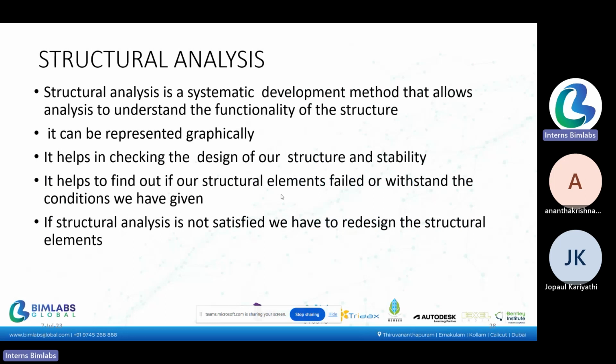Next, it helps to find out which element failed or which is able to withstand the loading condition which has been given inside the whole structure. If anything has failed, or our beam is not capable of handling this much load or pressure inside this whole structure, we have to redesign it. If the structure analysis is not satisfied, we have to redesign the structural elements.